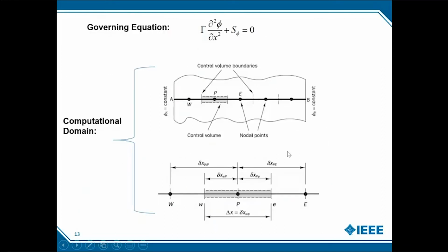Now we have this equation at the face e and face w, but all the values that we know of phi, of gamma, are at the nodes. We don't know the value of these things at the faces. So how do we calculate the value at faces? It is basically just to interpolate. That's the only way. So you have something at w, say gamma of w.